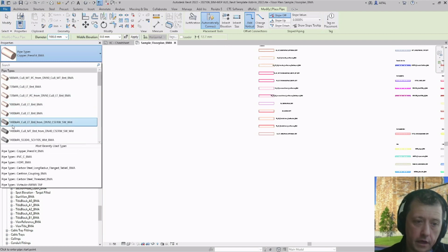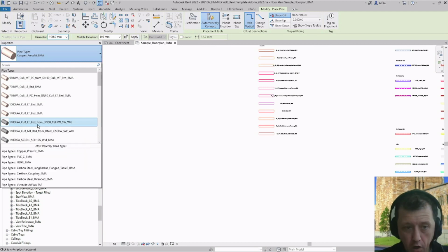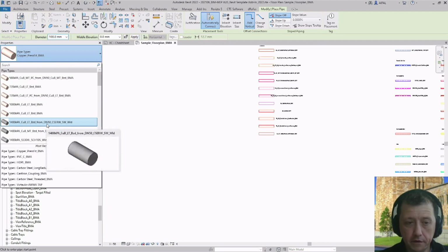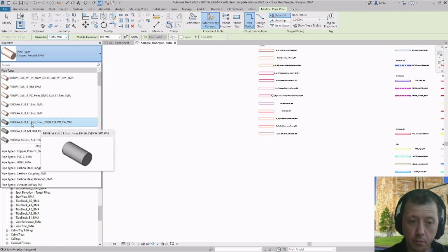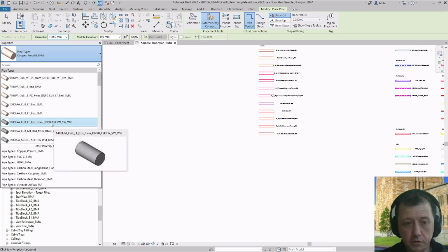You have here the safe working pressure, 1,400 kPa, for example, and up to the pipe size DN50, you can in that case use a copper B brazed pipe, but as soon as you come to a DN50 or larger, you should use a carbon steel pipe welded.